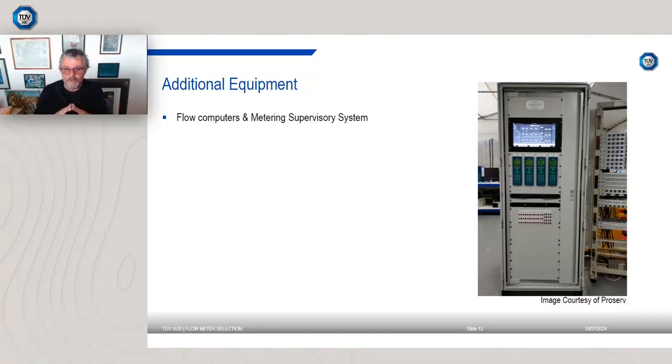That usually contains flow computers, purpose-designed hardware, which can take information such as pressure, temperature, flow rate, density, gas composition, and valve position. It can take all that information together and allow the operator to control and take information from that system in a safe environment and in a user-friendly way. But again, to labour the point, they cost money, they weigh something, and they take up space.